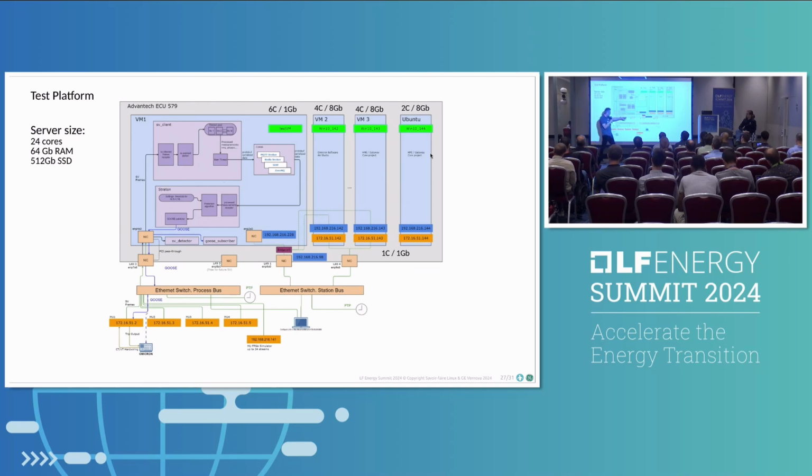In our case, our hardware had 4 physical ports. This is external to the server, so we deployed one Ethernet LAN for the process bus. The process bus is in charge of collecting the sample values through merging units. And we prepared another network for the station bus. The station bus doesn't need real-time requirements normally. Okay, everything that is flowing through the process bus does need real-time requirements.